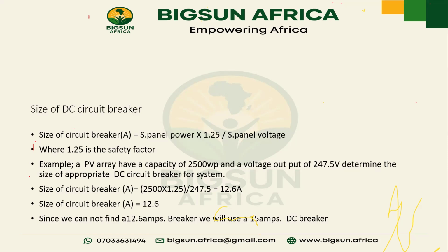Just a question. This voltage you're talking about, is it the total output voltage from the panel? The total output voltage of your connection, yes, the one you got from the meter. Maybe you are going for system 12 volt. When you connect your panels in parallel, the overall voltage you got is what you are going to use for your calculation.